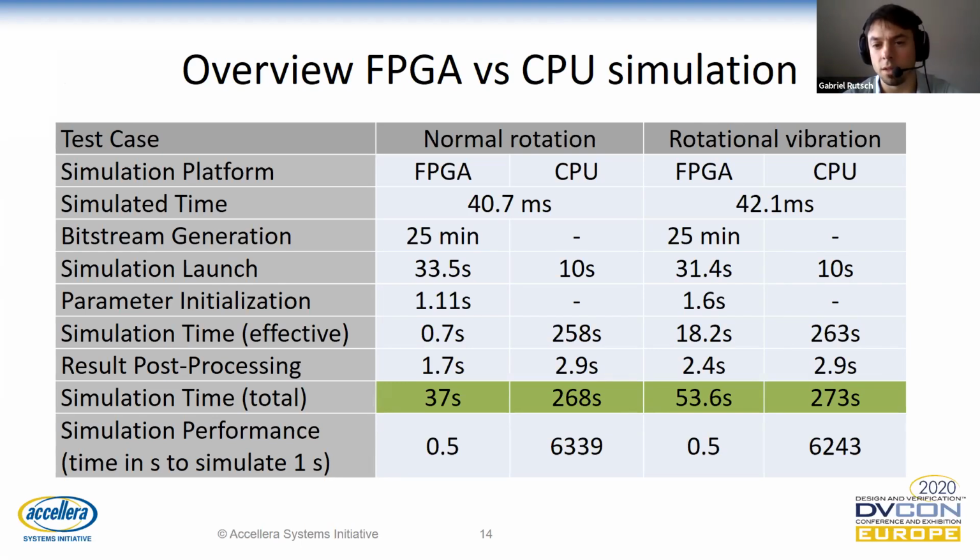On the CPU case, this is typically reading precompiled objects and elaborating the design, anything that is necessary in order to start the simulation. On the FPGA, this means starting the framework, programming the bitstream, and initializing some of the additional instrumentation on the FPGA, which does take quite some time if you use the standard Vivado tooling. Then, since parameters are runtime configurable, this also needs some time to initialize those values.